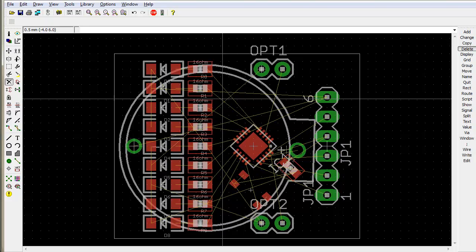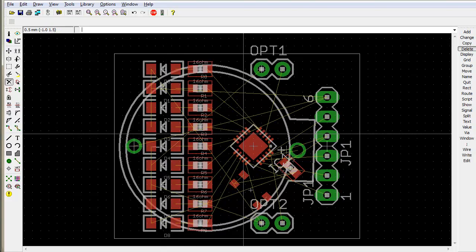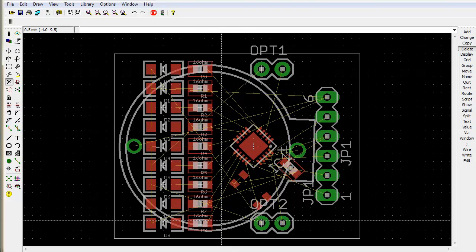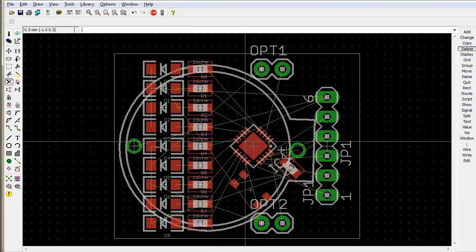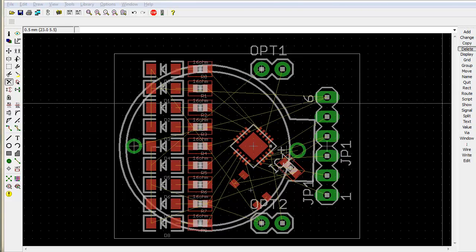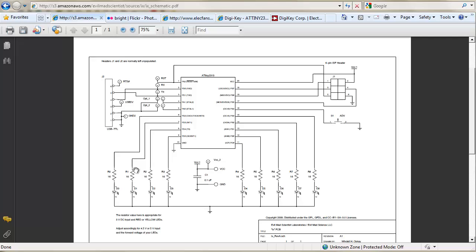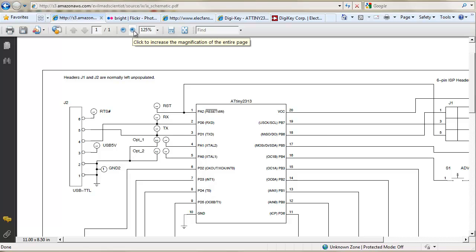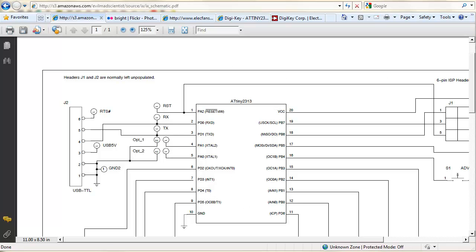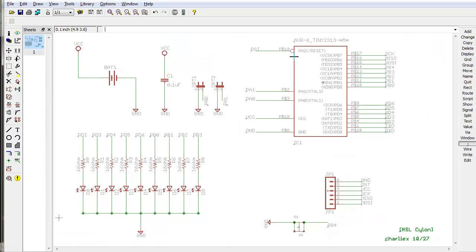Now if you can ignore the battery and look at these, you'll see the fan effect that's coming away from this chip. So these lines here, see how they're going to the LEDs now. If we look at the original schematic, you'll see that same kind of fan that's going around. So there's the LEDs. But what's different about Doctor Who's schematic is that his goes 1, 2, 3, 4, 5 all the way around, so it's the numerical order of the chip. However, which isn't that uncommon, in our schematic you can see the numbers aren't there, they're grouped by the function of the chip. So you don't get that necessarily nice layout, so that's one of the reasons that I don't do it.